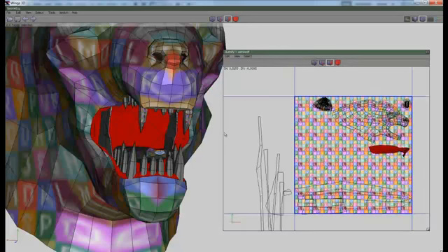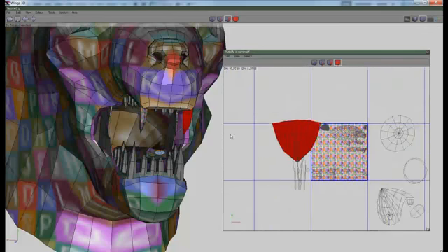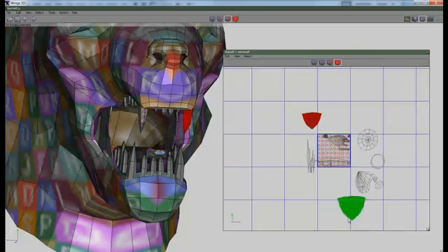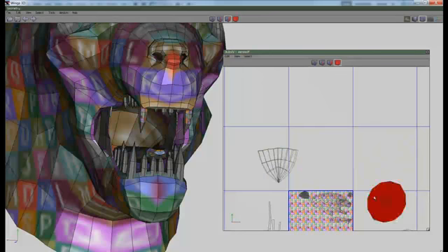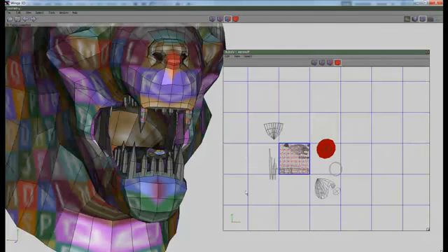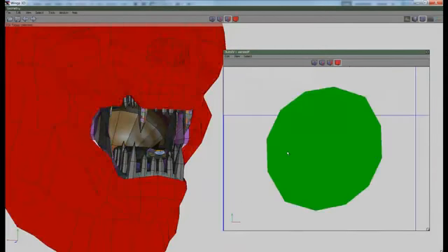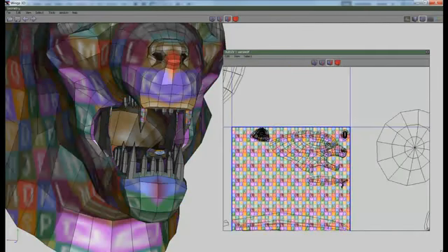But yeah, this is really the perfect moment where you can bring in your model and your map into Max, and then just sort these out, make them the correct size so that the pixel distribution or pixel to size rate is equal across the entire UV map. Redo certain areas like this, and also clean up certain areas using the tools in Max to really just perfect this.